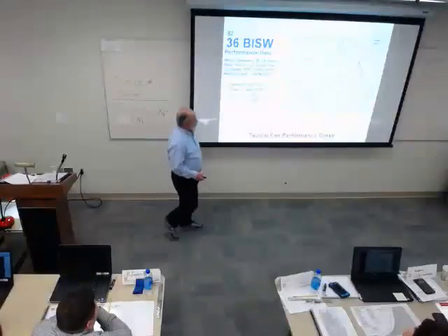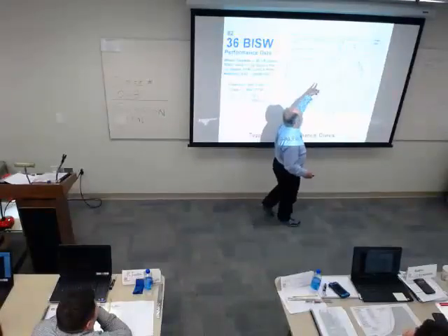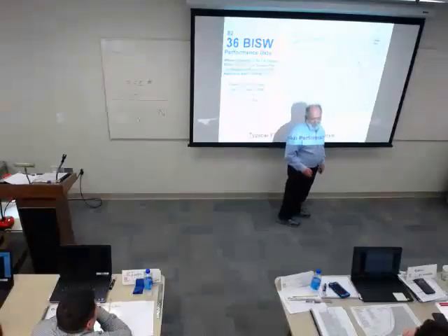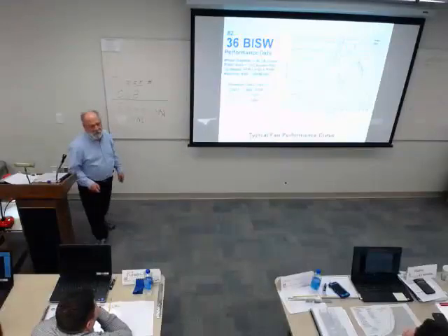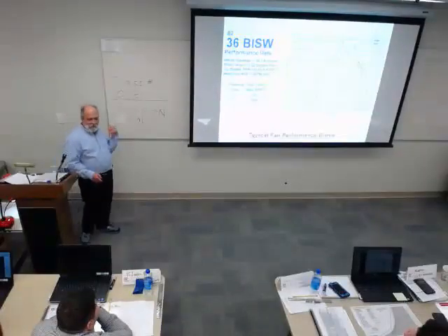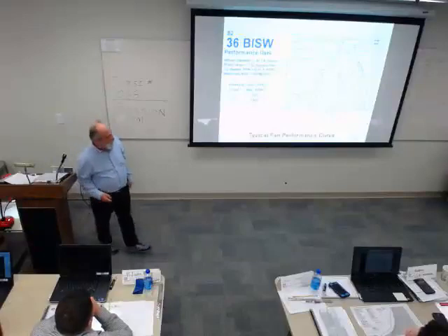All right, this is what we call the surge curve. Do not select left of this. I mean, how plain can you get? And yet you'll have manufacturers' reps selecting it like that, submitting it with the selection on that side of the curve, and expecting you to accept it.